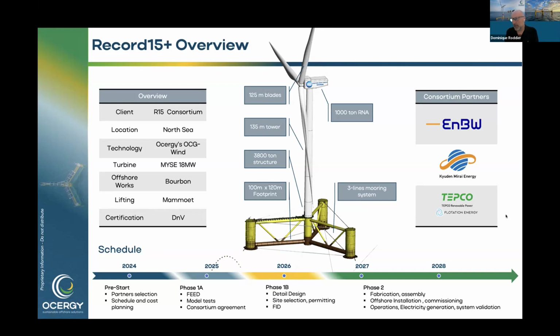And then the other thing you have to look at is, like everyone's talking about, the super grid. What if you have solar and wind, and how do all those mix? Electricity can move back and forth a lot faster. You all know the duck curve in California from solar, and then when you start adding everything, it becomes pretty much flat when you take the balance between the generation and the demand. When the sun goes down, the wind picks up, and so between wind and solar you're good, and then you can use gas to balance the rest.